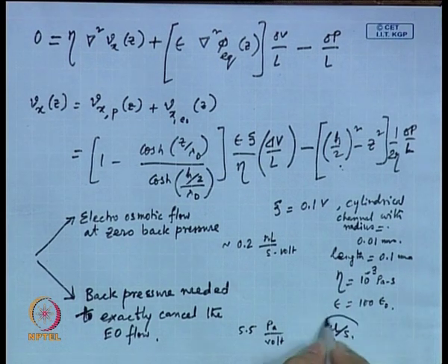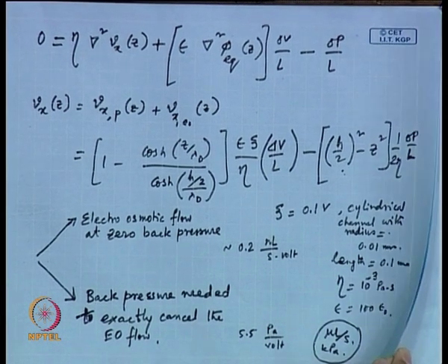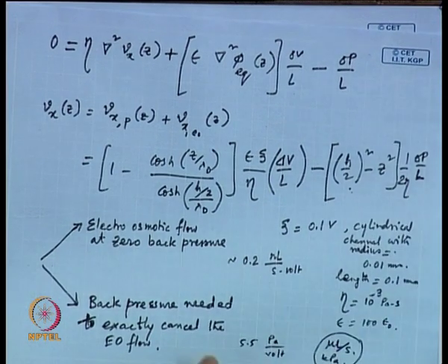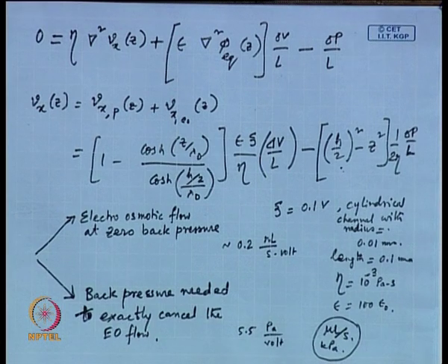These are very much possible with a channel with frits or closely packed glass spheres, so that you can generate a large number of parallel channels. Any electro-osmotic pump would comprise such frits inside the channel, or the channel would be packed with beads, so that several parallel channels operate.